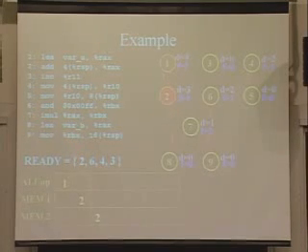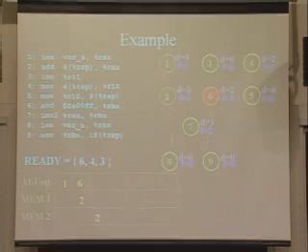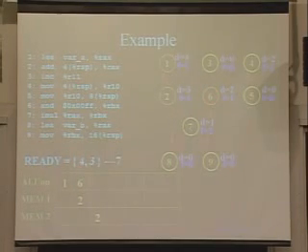So it's not really Tetris, you can actually move things inside out. And then you pick 6. 6 is an ALU operation, there's no memory, so you move 6 there. And at this point you can put 7 in there. So you can pick 4. The interesting thing is 4 is a memory operation, and it's not depending on anything. Now it can actually move in front of 2, because we had this empty space in there.